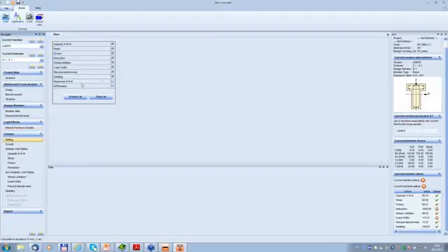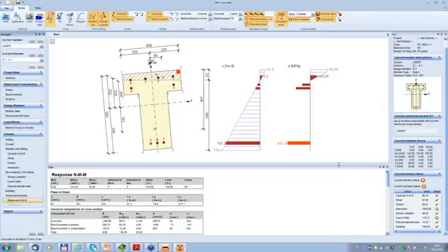In settings, you can say, for example, that you also want to have stiffness or a response. In spite of the fact that I see there are some checks which failed, I will show this response first. This is a stress-strain response of the cross-section which we are going to design. You see this is a strain distribution, and here is the stress distribution.